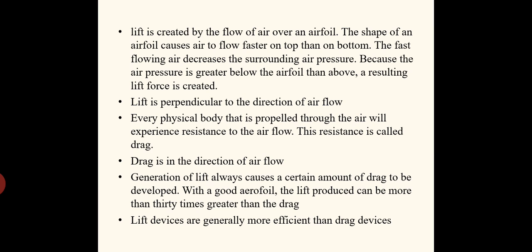See, that velocity difference at the top and bottom layer is created by the shape of an aerofoil. The fast flowing air decreases the surrounding air pressure. Since the fluid at the upper part has to travel with more velocity, of course the pressure will be less. So at the expense of the pressure, kinetic energy is increased there.